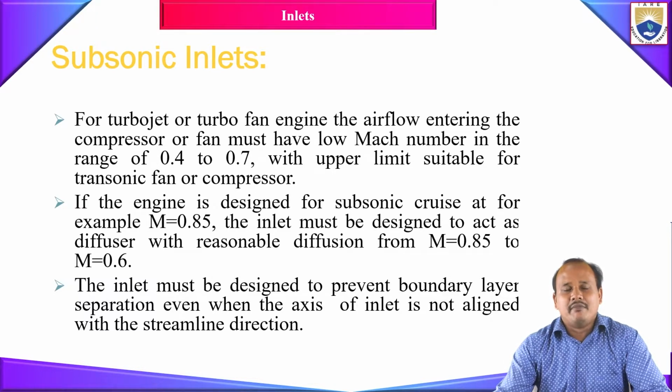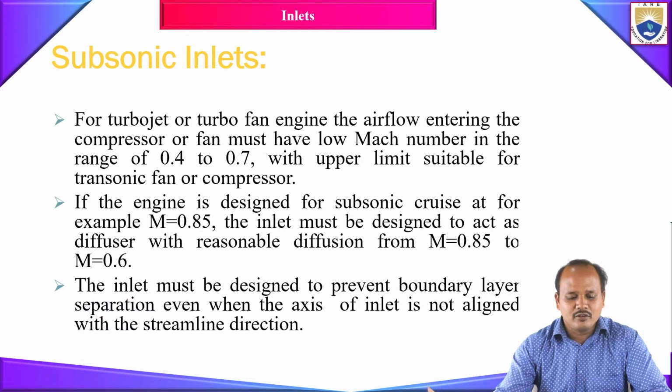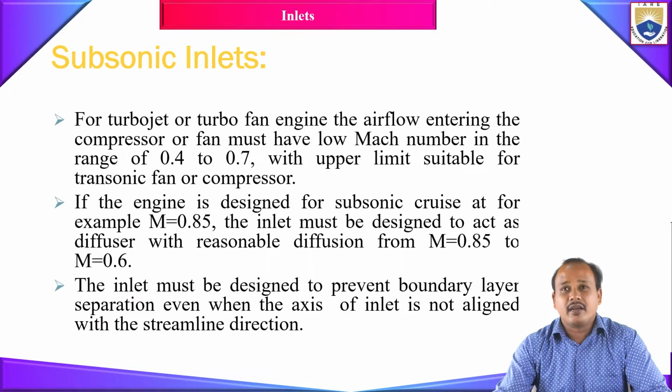What is the Mach number of your subsonic flight? That's up to Mach number 0.8. We call it subsonic. So 0.8 to 1.2 is transonic. So subsonic means your flight is going to be flying at less than 0.8. So obviously the flow encountered by your intake is also going to be subsonic. That's why we call it the subsonic inlet, or subsonic intake.